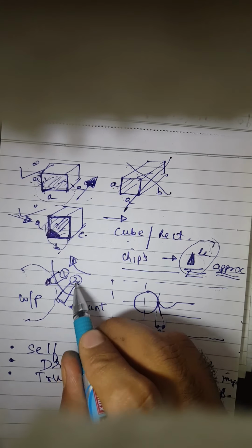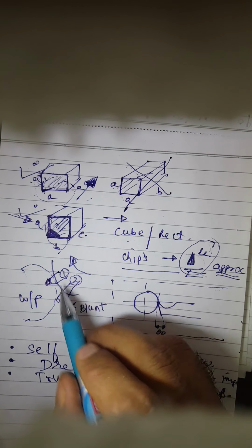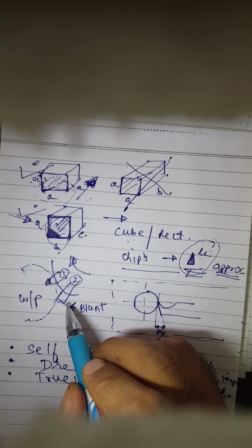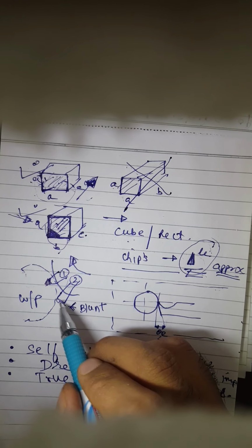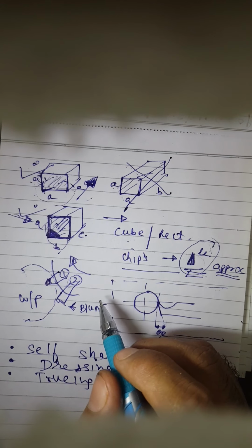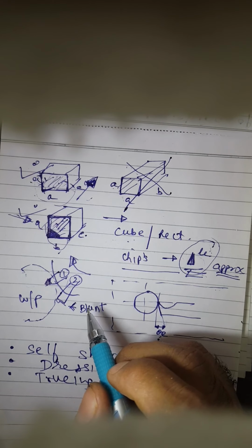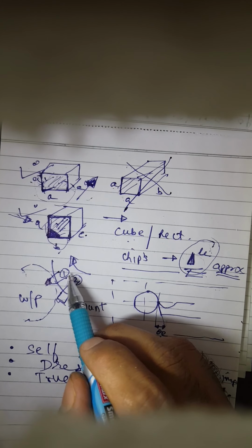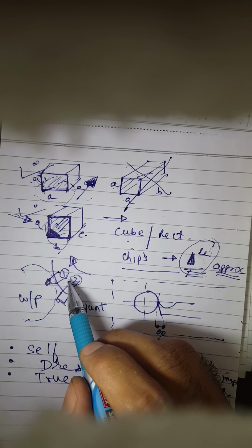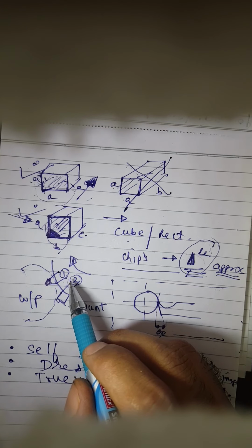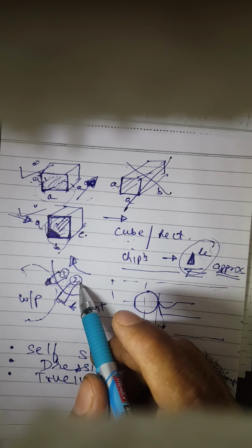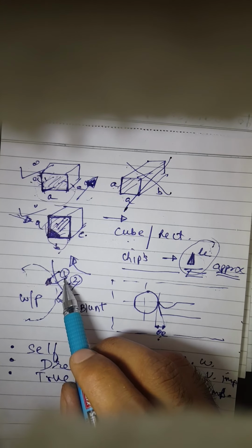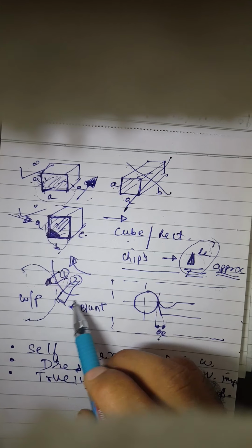Why blunt? Because as we had seen on a previous page, this particle number 2 is only performing the rubbing action. It is not removing material from the workpiece, which means that it is nothing but a blunt edge that we may have. So when this particle number 1 gets blunt, obviously it is not going to perform the cutting operation, but rather it would result in the rubbing action that is taking place.